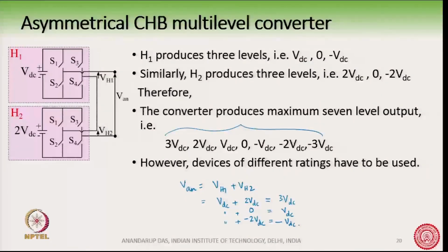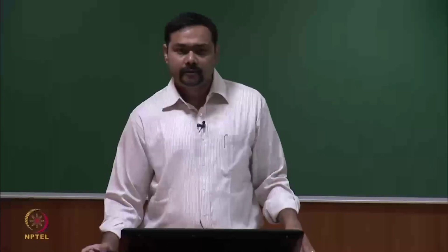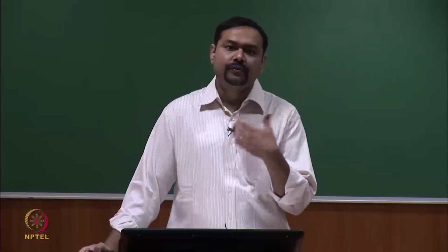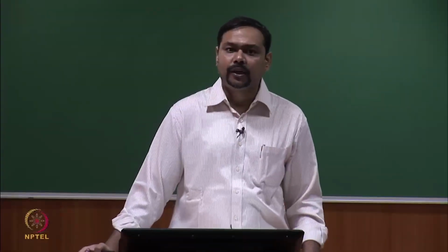For H1 we will need devices of voltage rating VDC, and for H2 we need devices of double the voltage rating. So, we lose the modularity, we lose the repeatability, we have to have 2 sets of cells available to us.